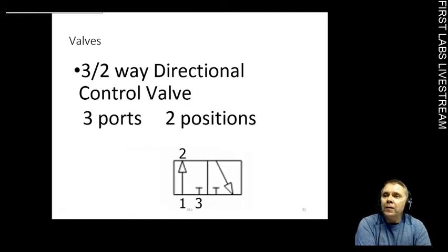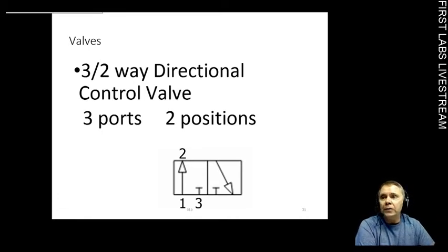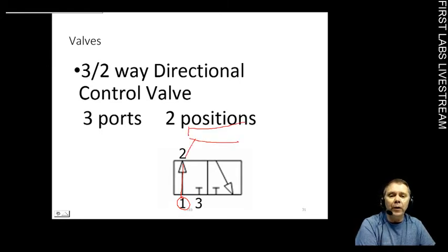Now, when you operate the valve, it slides over to the other position. And you can see now from port 1 right here, the air can now flow through out to your cylinder. So if you had your cylinder attached at this point, and it's a spring return cylinder like that, and there's your port input, the air would flow in, and it would push the cylinder out.